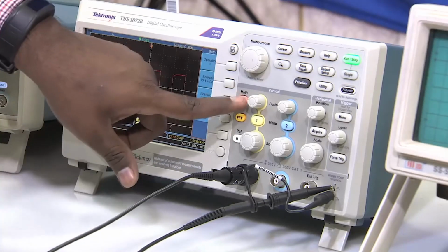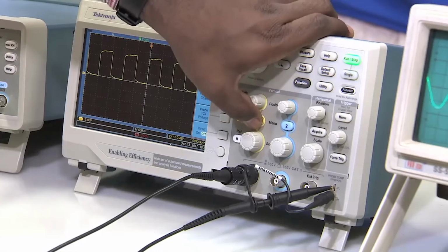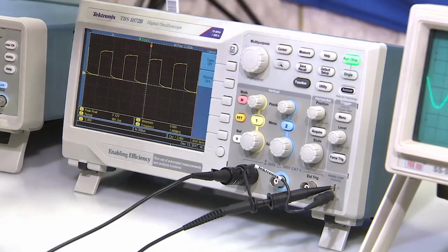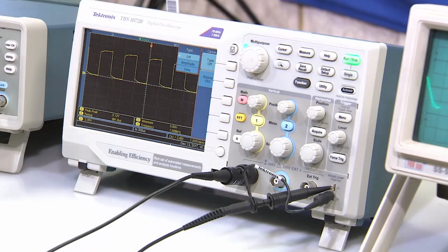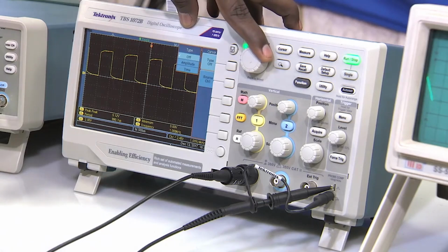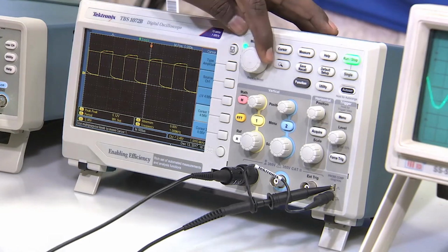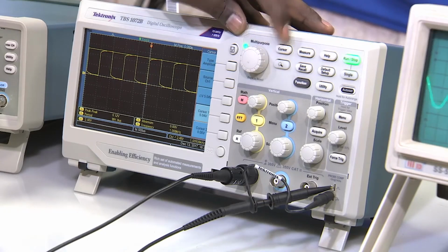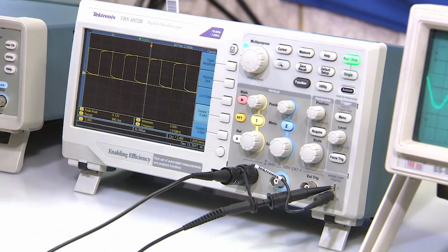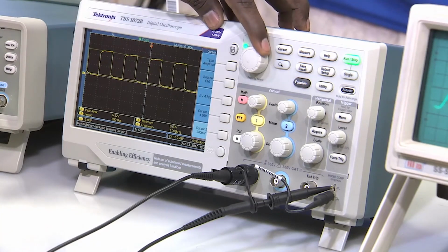So, these are several buttons on the oscilloscope, alright. Now, other than that we have the cursor on the top, and then you can choose whether you want it on or off, whether it is amplitude or time. Let us say you want amplitude. Pressing amplitude, I will see one cursor at the top of the waveform, and another one should be at the bottom. So, cursor 2 you can have at the bottom.